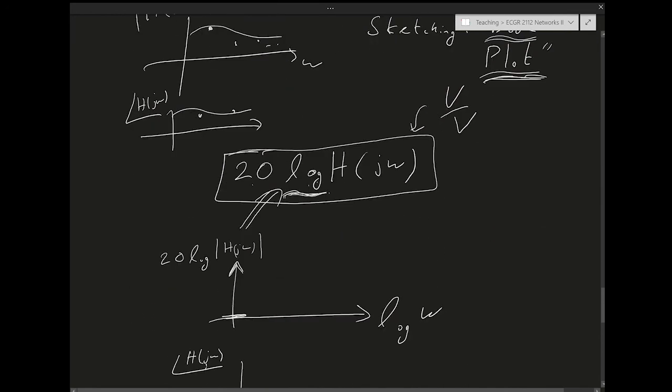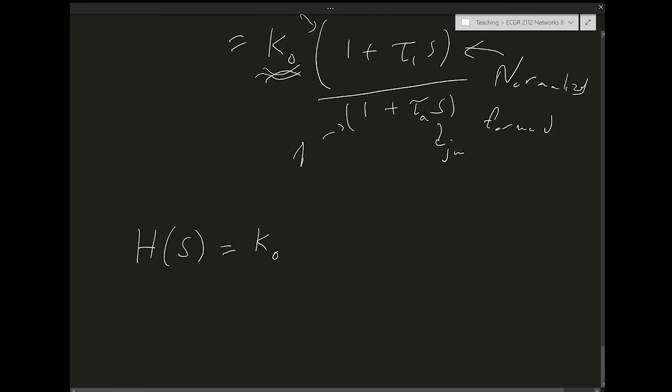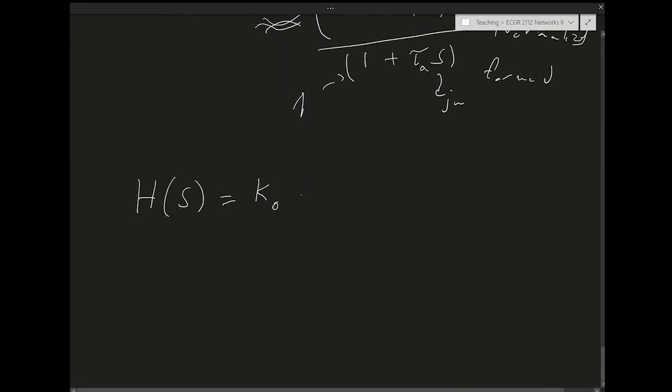So we could have expressions, what's called zeros and poles at the origin, at s equals 0. So this would be s to the m. We could have m zeros at s equals 0, over s to the n. We could have n poles at s equals 0, right?